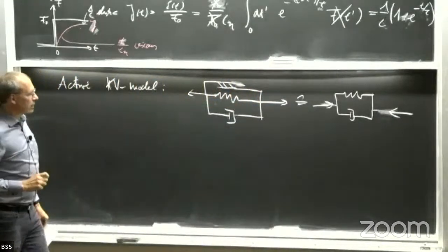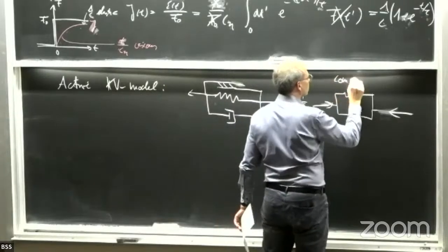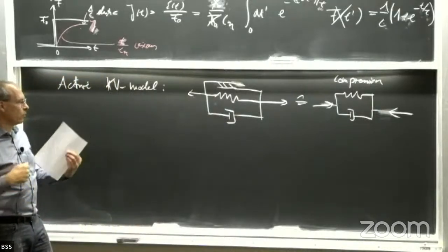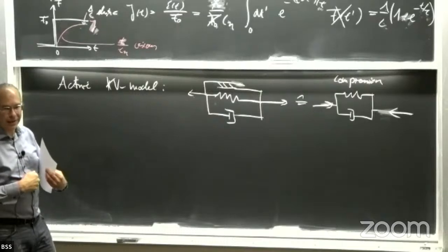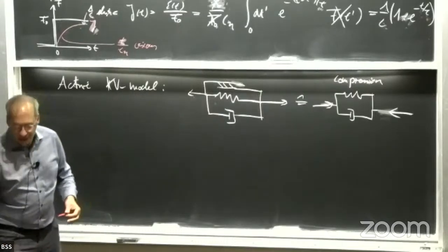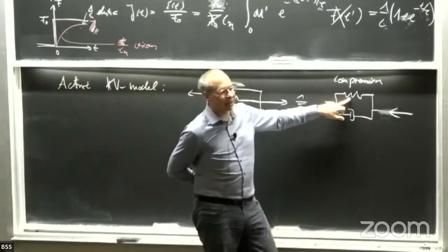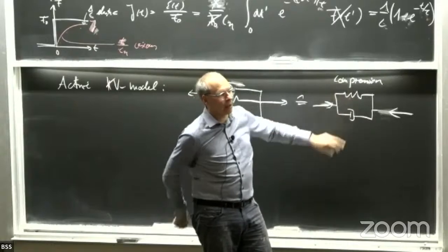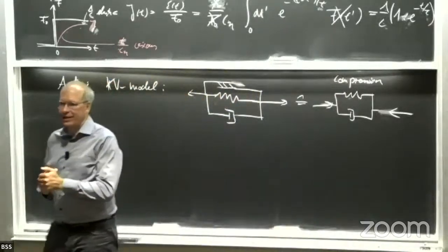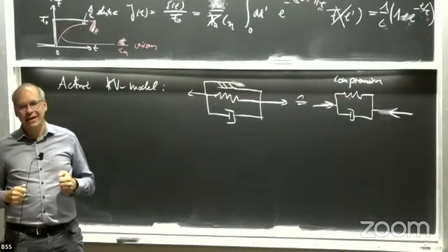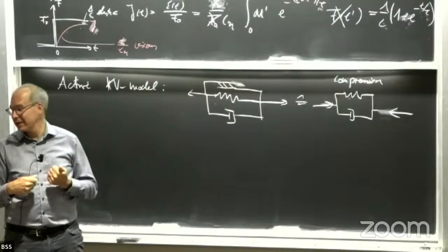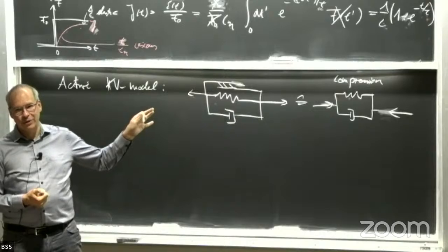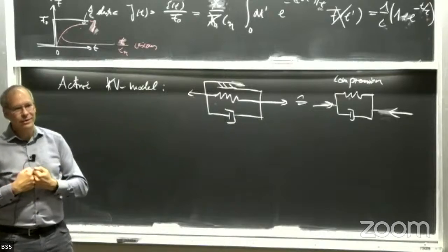So when I said that this is unphysical for the Maxwell model, because if I compress it, I push in a lot of length, okay? It looks better now, right? Because the spring can keep it, okay? The model is okay because the spring can keep the compression. But last week you were actually instructed on polymer physics, okay? And you know that polymers don't do it. So polymers buckle under compressive load, okay? So the model is fine, but in our context, it's also bad. Because how should a polymeric system do this, okay? So you have to think about how this works.